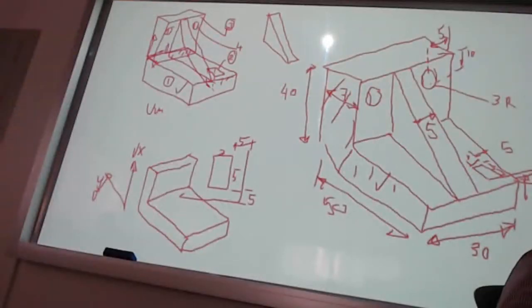You get this one, guys? You see how much I saved? I just draw that shape, step number one, and then press pull to come up with step number two, and then I'm going to locate the circle here. Okay, two circles and one rectangle. And after drawing all these three shapes, just make press pull for this one, for that one, for that one. You end up drawing most of the shapes in two steps, or at maximum three steps so far, right? What is left, guys, is to draw the wedge.